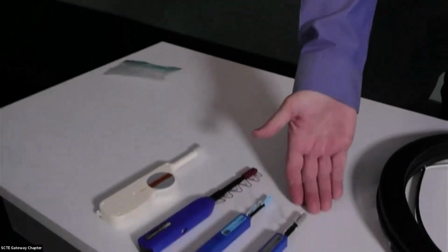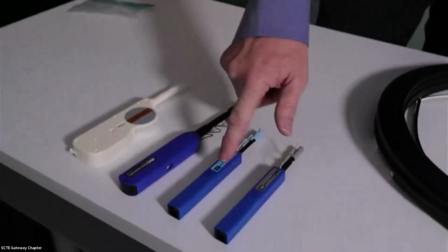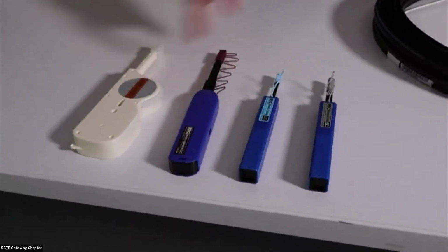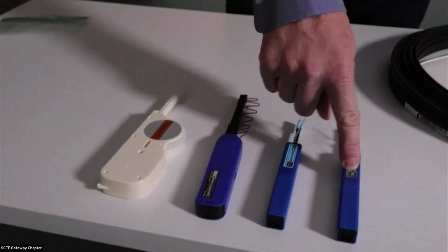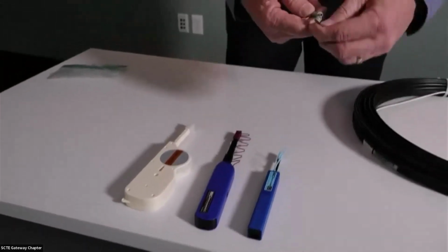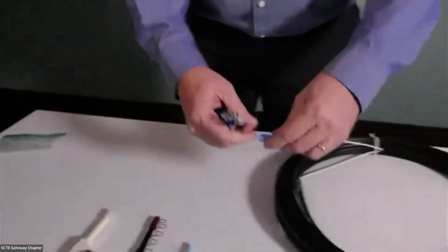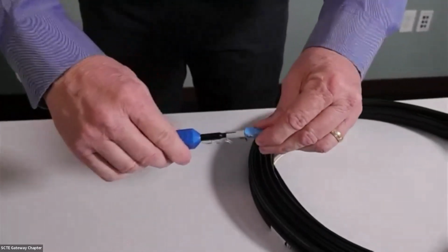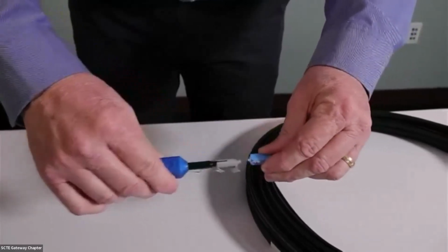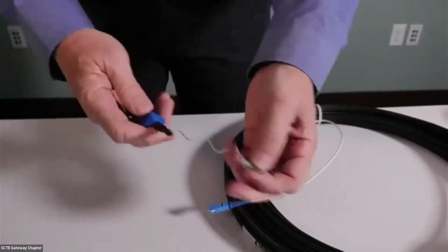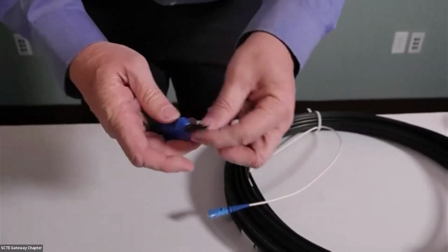So this is an SC cleaning pen. Depending on your brand, they usually have a description of what the pen is for right on the side of it. So an SC, remember that's the bigger square ones that's going to be used most common. A cleaning pen, you flip the top off, and that's for cleaning a ferrule. Designed for a single push. Every time it clicks, that's a rotation of the cloth that's on the inside. Pushing will drag the cloth across the end and clean off the dirt.